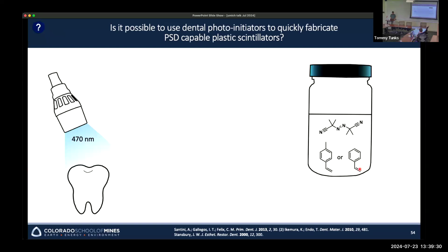So this kind of goes back to my PhD here at Michigan, where I worked on dental materials. With dental materials, for composites, that's all done with light curing. I don't know if any of you ever had a filling done with one of these, where they're shining that blue light in your mouth. This is exactly what's going on. So there are monomers there. In the case of a ceramic filling, it's mostly some kind of silica and zirconia filler that is integrated in, and it's kind of like a toothpaste consistency. If you take some of these filler materials and dilute them with some reactive species, you can get it into this toothpaste quality that you can fill and shine light on. And so this is exactly what's happening.